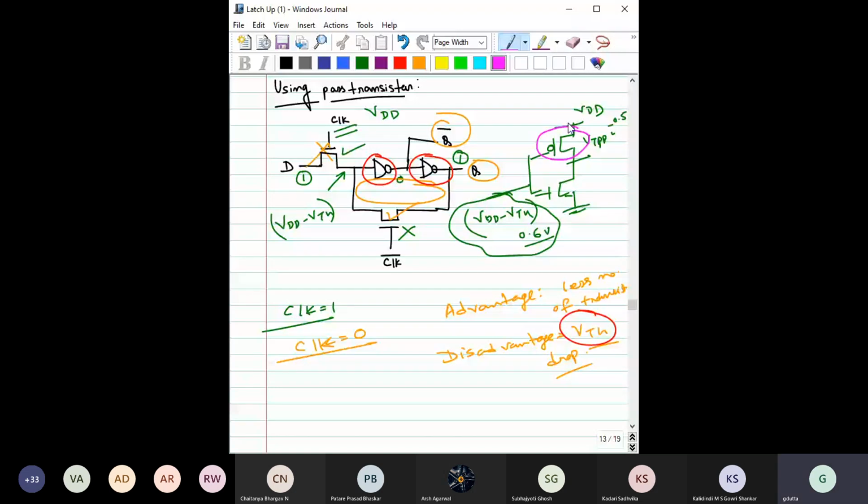Slightly on, right? It has just 0.1 volt overdrive, it is above the threshold voltage by 0.1 volt. So there is a possibility that this MOS is then on. Anyway, this is on, and this is also on. So there is a possibility of static power dissipation. That is the reason why it is not good to have one threshold voltage drop at this output if you want to use that to drive a static inverter afterward, or any static CMOS gate after that.